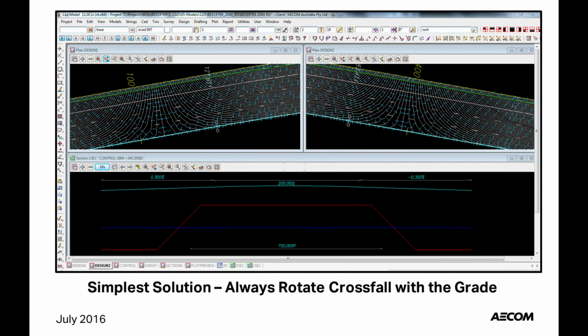So the simplest tactic is always to ensure that the road grade runs in the same direction as the crossfall change. A grade of 0.3% will always ensure that the resultant pavement slope never gets flatter than the absolute minimum. And the alternative is to provide a much greater upgrade, usually around 2.5% for a three-lane rotation, to ensure the resultant surface grades stay above minimum.